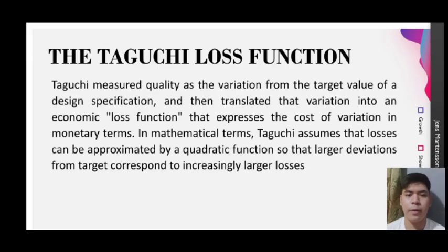Taguchi loss function. Taguchi measures quality as the variation from target value of the design specification and then translates that variation into an economic loss function that expresses the cost of variation in monetary terms. In mathematical terms, Taguchi assumes that losses can be approximated by a quadratic function so that larger deviations from target correspond to increasingly larger losses.